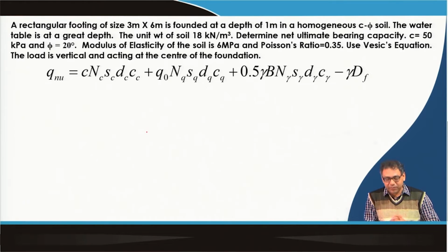But here, if we have the modulus of elasticity or shear modulus or Poisson ratio, then automatically we can understand whether this compressibility correction has to be applied or not by calculating the critical rigidity index and rigidity index. So, let us see whether in this case the soil compressibility correction is required or not.